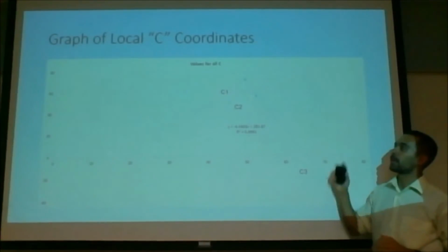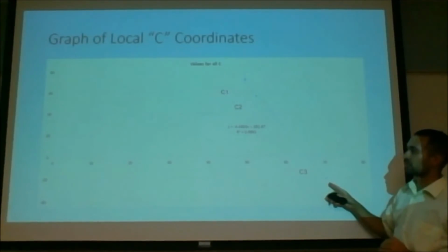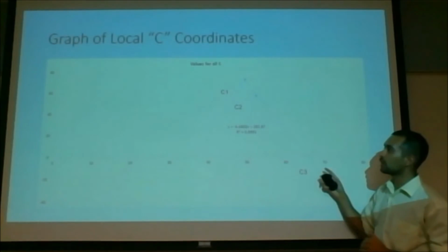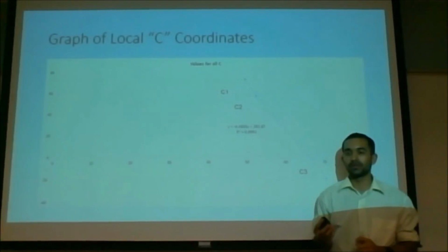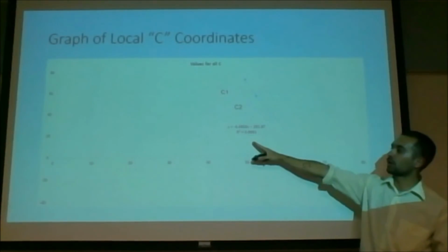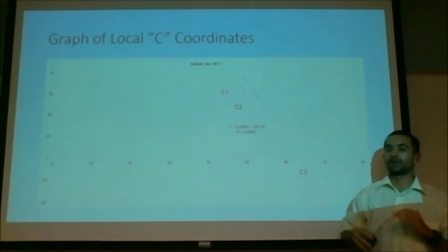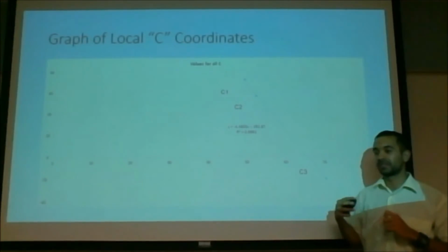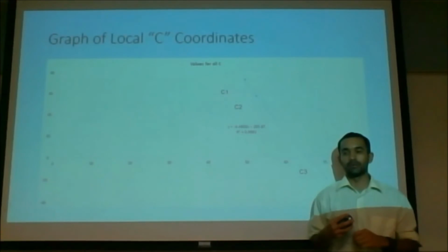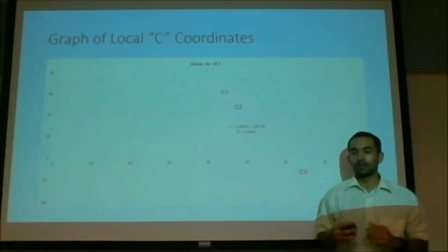As we can see, all points are almost aligned in the same line, meaning that our system is fully synthesized, given our values are correct. And here the R squared tells us that our values are very close and accurate, meaning our crank slider mechanism will be synthesized and can be used in many types of applications later on.